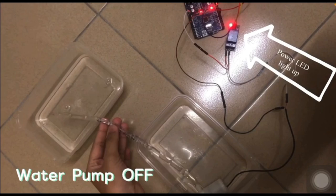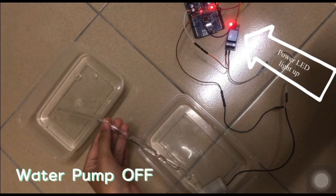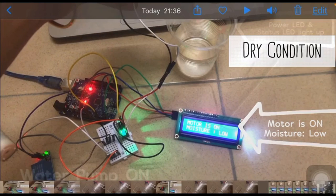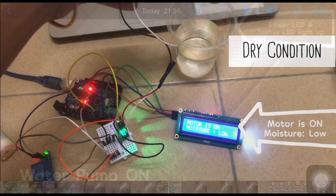Next is the second condition, which is the dry condition. For the dry condition, put the soil moisture sensor above the cup surface without sinking it. The LCD display shows that the moisture content is low, which is the value greater than 915, and the motor is on.